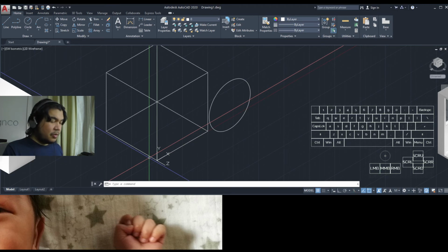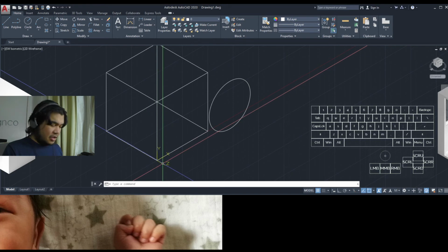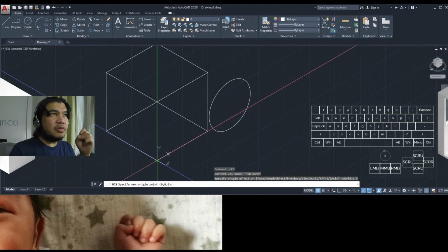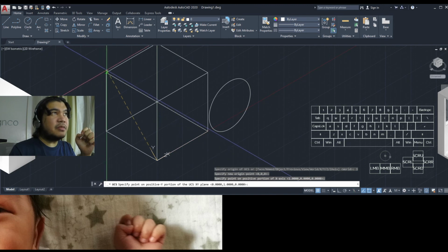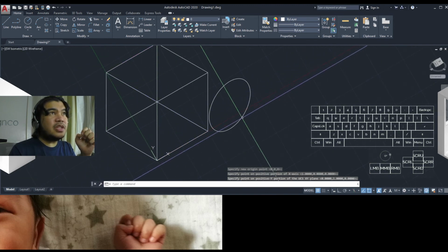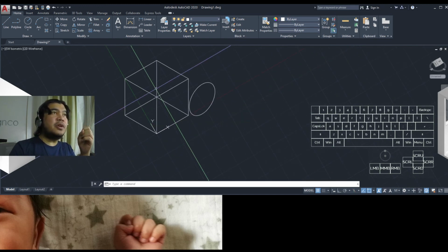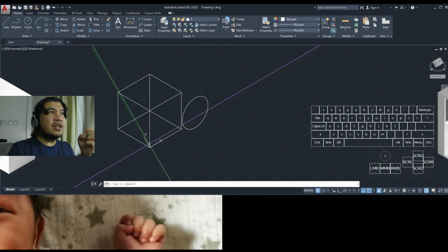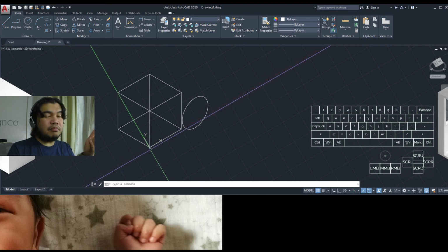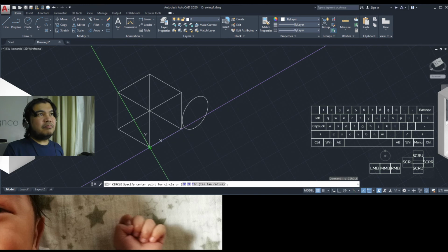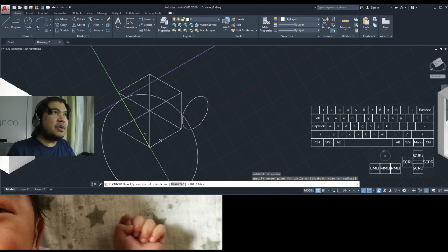another 3-point origin translation. So we will do that manually, and by that I mean not clicking on the UCS. It's by doing UCS 3. So now we identify the origin, positive X and then positive Y. And then you can see that the origin or the UCS has now shifted to a 45-degree plane of, let's just call it a paper.